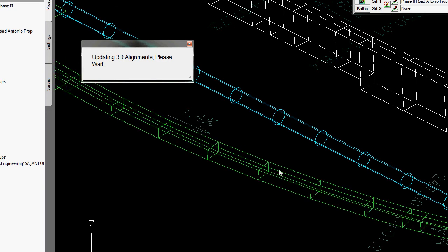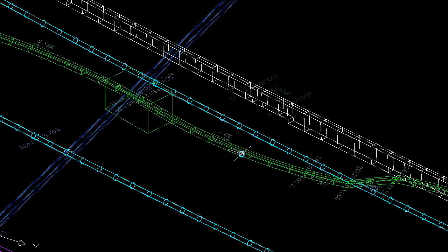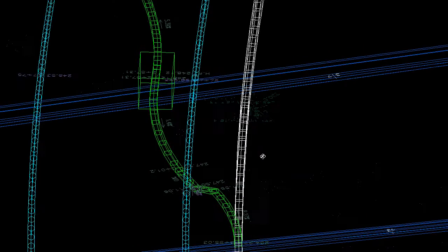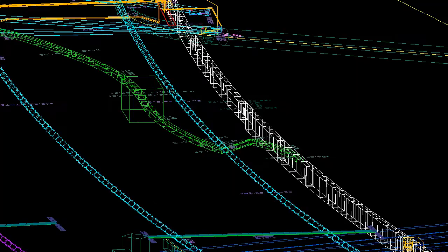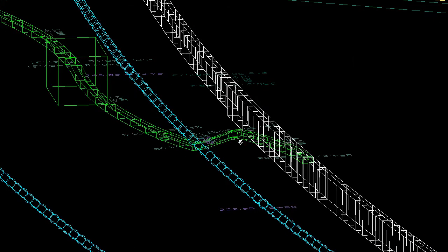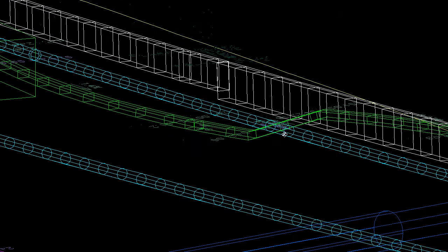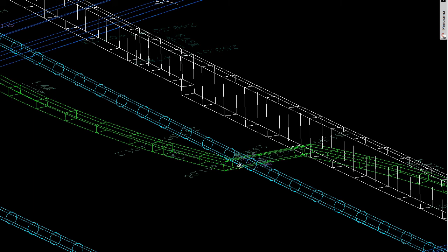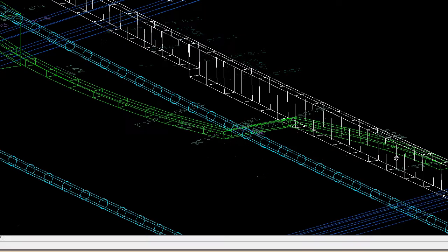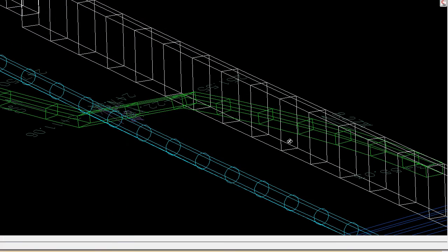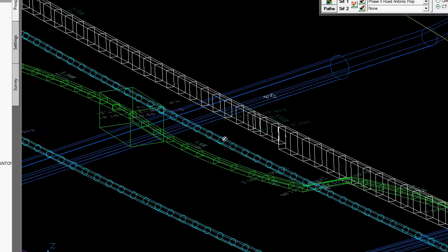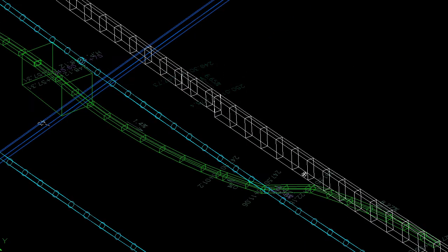So now I can see I'm coming out of this joint trench, coming down, and again, this isn't reality either. There's no grade breaks in conduit. This is going to have to be a smooth sweep that comes up here. But I'm going to leave it like that for comment when people look at it, and they can kind of decide. Dry utility plans don't have profiles usually, so. But they do need to know that if there's a pipe here, here's the crossing under, and I want to model it to try to reflect what the thinking was on that when we did it.